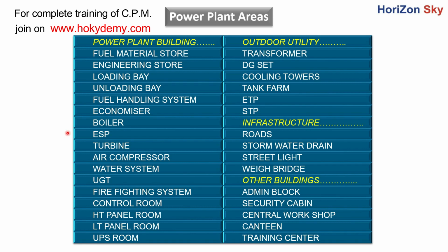After that, using, as the name suggests, static electricity, these components are shaken off from these plates. They are generally ash or soot. From these components, the ash is collected at the down part of the boiler, and fly ash bricks are made from them. That is a byproduct which we don't otherwise need or use. These are mainly a part of the thermal or biomass power plant. So the main function of an ESP is to control air pollution of the gases leaving our boiler.